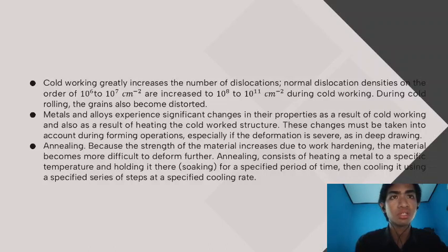This microstructural change during annealing has different effects on properties. Grain growth is almost always an undesirable process because fine grain material offers the best combination of strength and ductility. During recovery, the strength and ductility are largely unaffected, but many physical properties are recovered to their original pre-cold working levels.